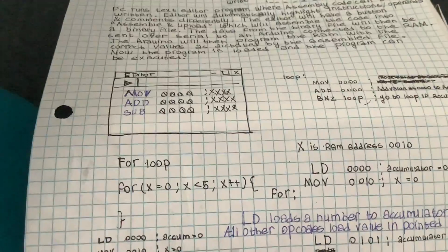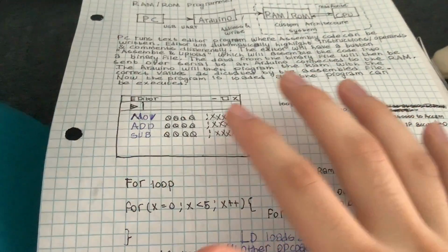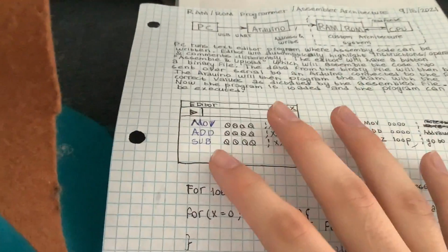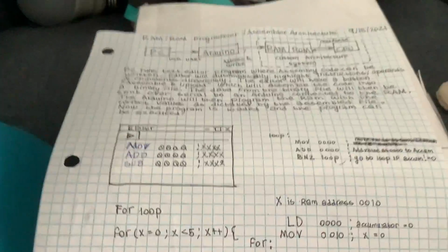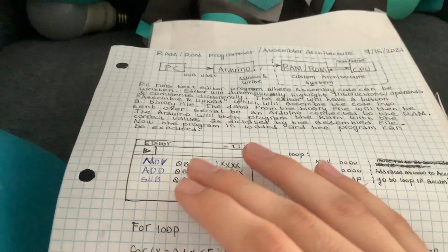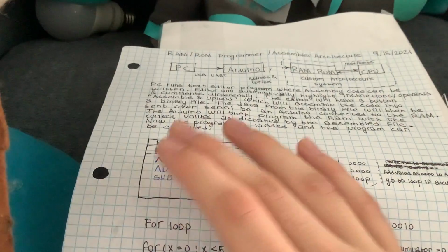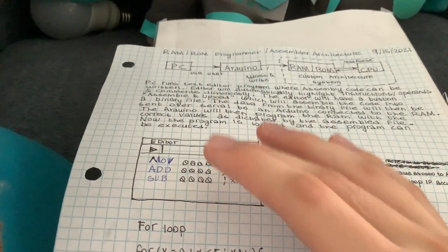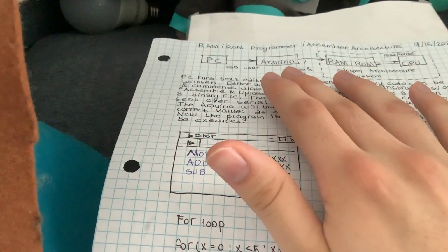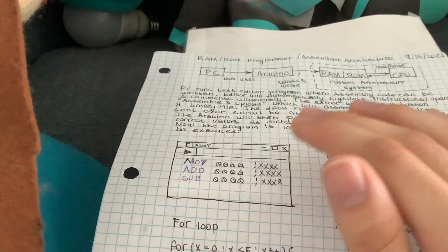So what I'm going to be able to do is to write out the instruction, the operand, and a comment. And I also want these to be highlighted as well, as you could see. And what this will allow me to do is to write the assembly program just in the text editor. And then by pressing the play button, that would be here, the PC will connect via UART to an Arduino, and this program will be converted into just binary data.